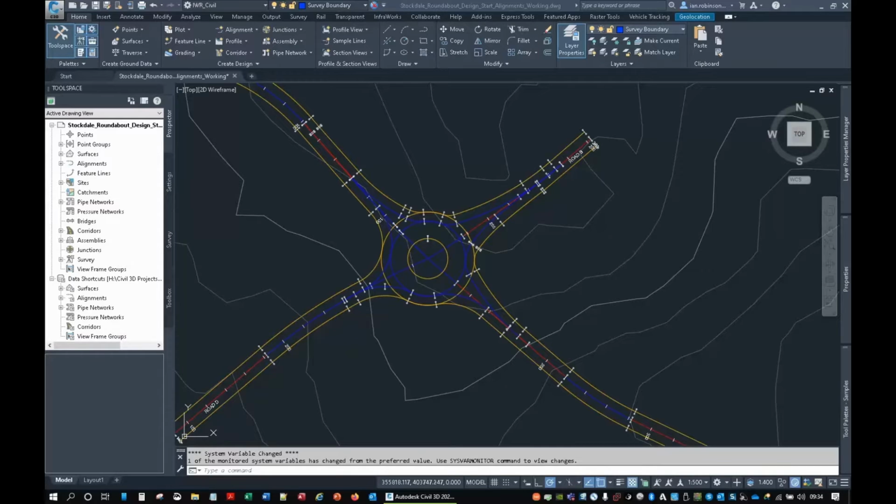First things first, we need a tilted plane. So I'm just looking at the contours and seeing that over here is high and over here is low. There's lots of ways of drawing a tilted plane. I usually just stick a polyline on there, or a line, and just run it across where I want to put it. I'm not bothered about the layer that it's on at this stage, because I'm about to convert it into a feature line. So I'll just do feature line from objects,